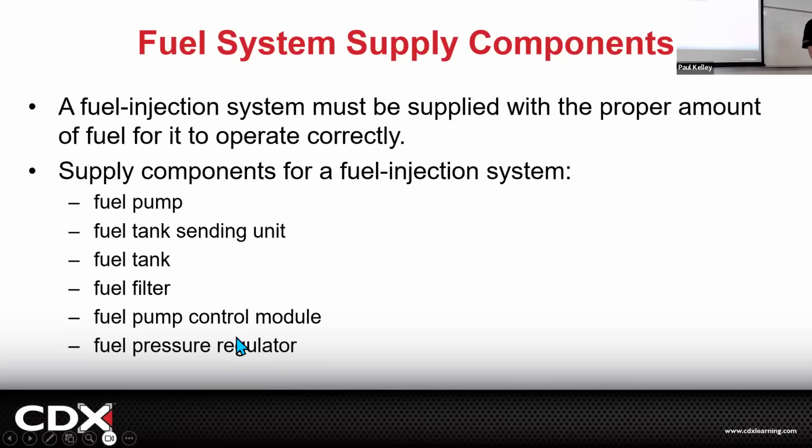And then the fuel pressure regulator. This one can get a little tricky. It's changed and moved. It does the same job, but it looks different on new stuff. It regulates the pressure. If we want 55 PSI of fuel pressure, we need the regulator to give us 55, not 48 at one point and 57 at another. You want it consistent so the computer can have a consistent reading and try to hit that 14.7 number. Remember that number? 14.7 is the correct ratio. If your fuel pressure is all over the place, the computer's going to be like, whoa, more, less, more. It's to stabilize that pressure.